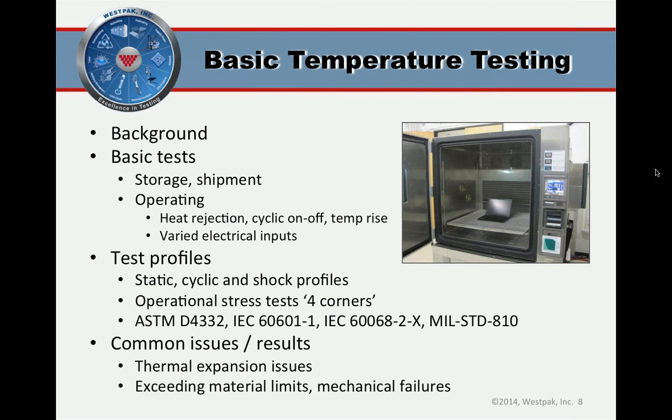First off, we have a temperature humidity chamber pictured here. This is a medium-sized one. We have our laptop in it. Some of the basic tests we'll run would be to simulate the storage environment, so just temperature and humidity extremes, and the shipment environment, and that generally is 3 conditions. You'll have a cold condition, a frozen condition actually, a desert condition, so warm and dry, and then a tropical condition, warm and high humidity or wet.